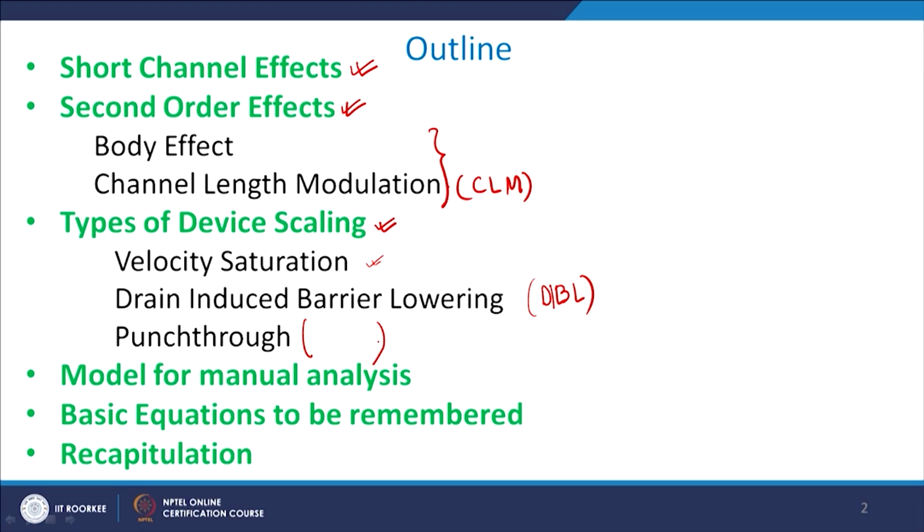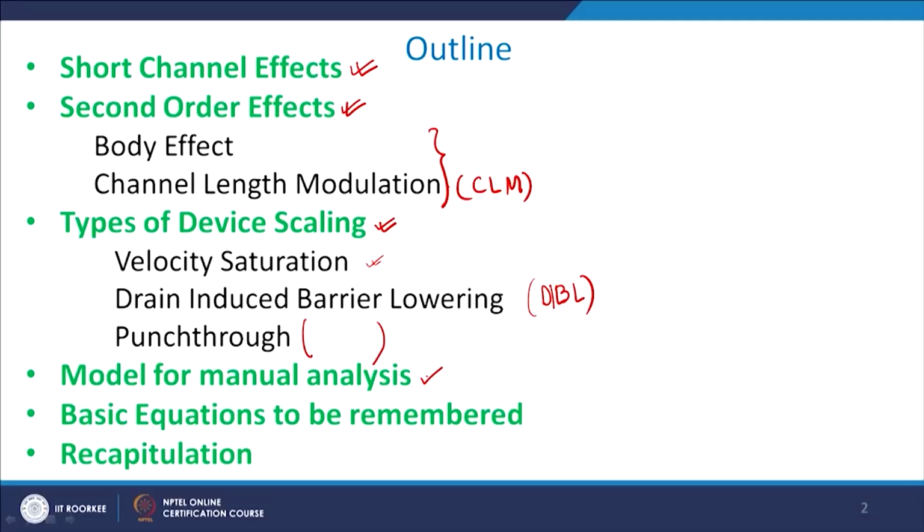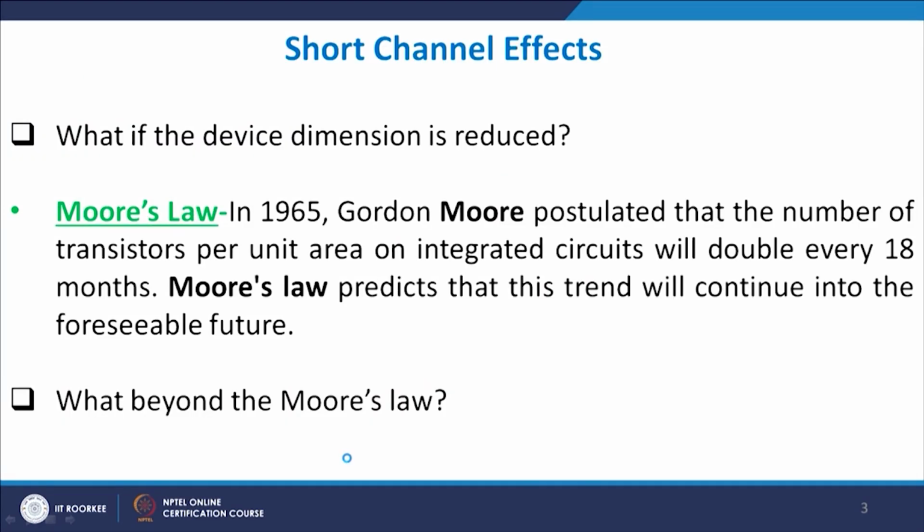Then once the MOSFET as a device is clear to me, we would like this MOSFET to be used for circuit simulation purposes. So can we have techniques for doing some amount of circuit simulation, that is, can we have some electrical equivalent models of the MOSFET which can be used for circuit purposes. We will also look at the basic equations which we need to remember and then recapitulate the whole talk. Let us look at the various short channel effects.